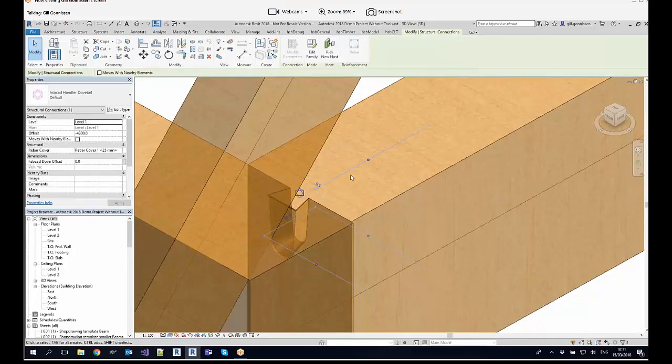Actually, now the most important part is that our hsbCad handler Dovetail is actually a Revit family being created by us. And behind this Revit family, we have attached some intelligence. We call that the coded family extensions. The coded family extensions actually mean some intelligence between the Revit family and how it reacts inside the Revit model.